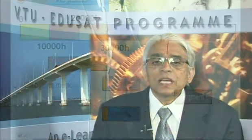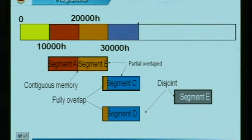Now, as has already been mentioned in the previous class, the segment registers are 64 kilobytes. The diagram here shows that there are different combinations of operations that are possible when you are trying to calculate the required address, where each segment's 16-bit value is added with the effective address to give the physical address.